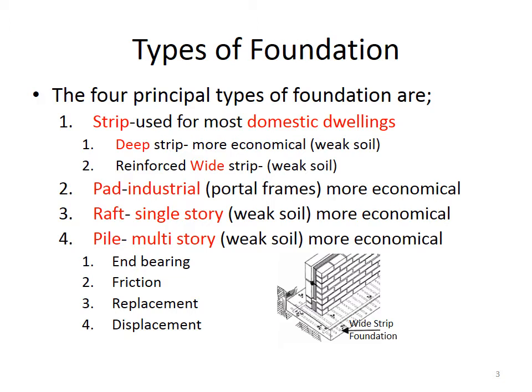The reinforcing bars run across the width of the foundation, and they're always on the bottom inside the foundation. Then they have connector bars running down either side in order to tie them in, so we have a nice structure when we're pouring the concrete in around them.